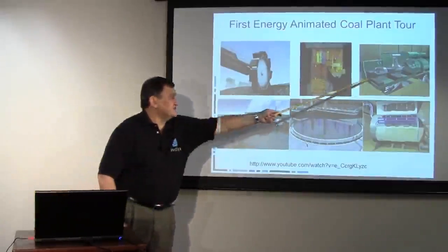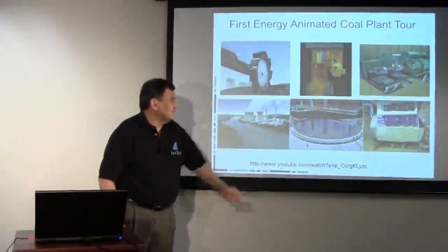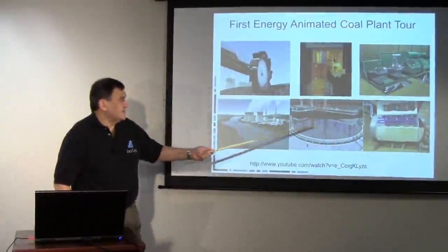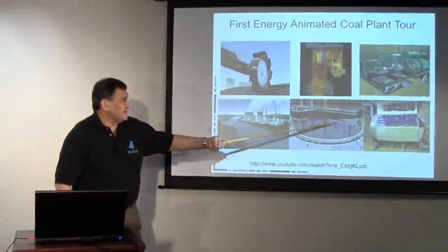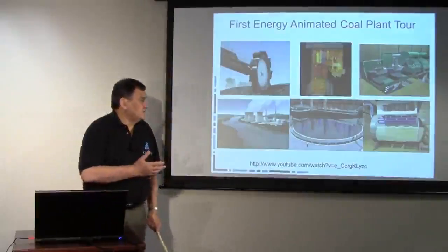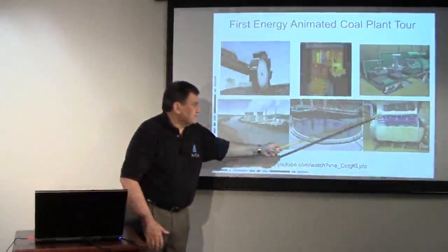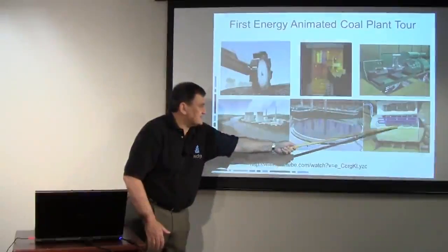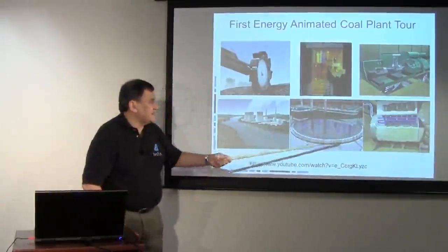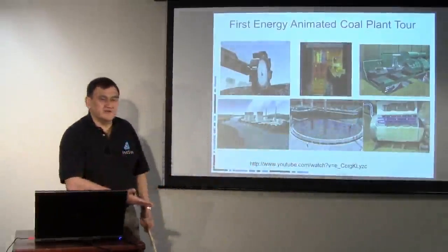They show you the three stages of the steam turbines. They show you the condenser. They show the effect of the latent heat of evaporation. Basically, the water that is helping with the condensing then goes through the cooling tower, and then the cooling tower decreases the temperature of that water even further.